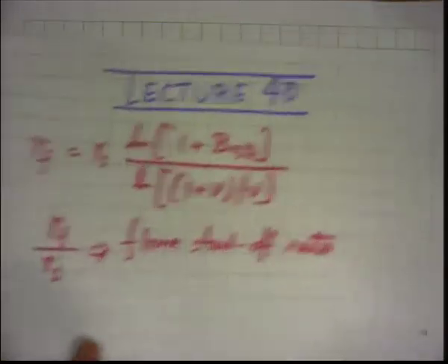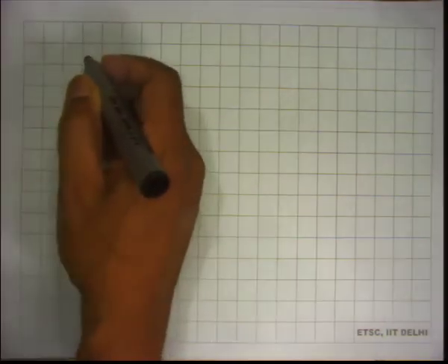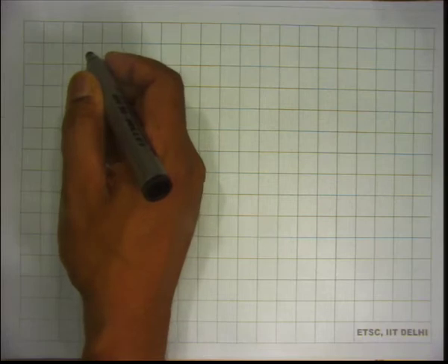What else do we have? We had a d square law for droplet evaporation, so we also have a d square law for droplet combustion. And you can derive that along similar lines to what we did for droplet evaporation. So for droplet evaporation, we say d/dt of the mass of the droplet is equal to minus m dot.